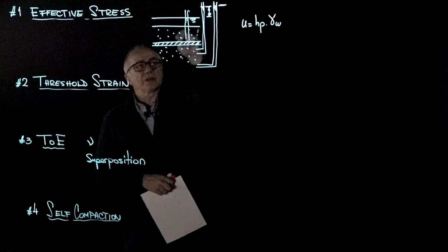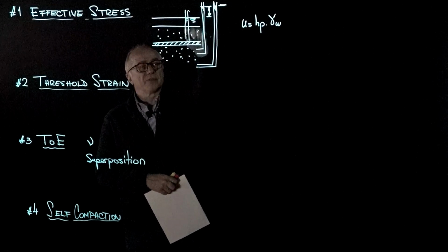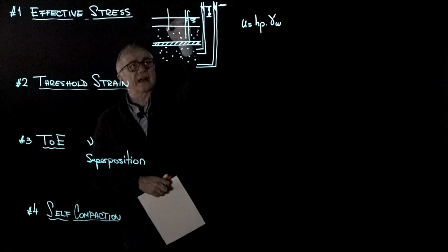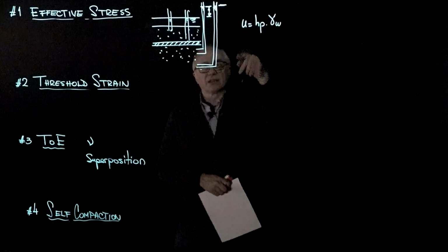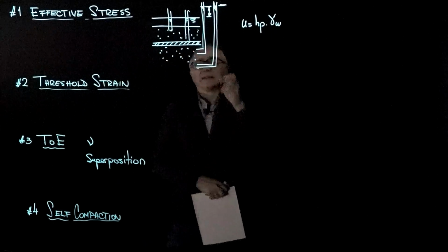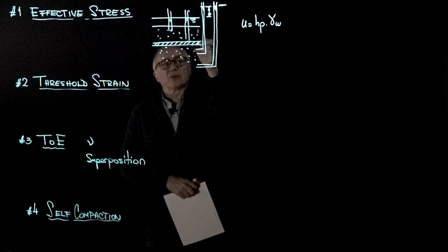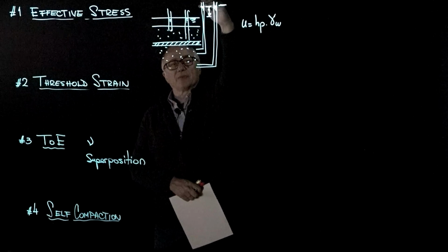Therefore, you know the pore pressure everywhere in the formation at the top because it will be the piezometric height at that point times the unit weight of water. Notice that the piezometer immediately below the aquitard will rise to this elevation here at the top.